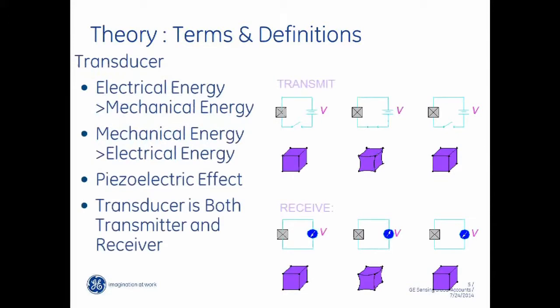So the actual transducer is nothing more than really a piezoelectric crystal that we energize and turn into mechanical energy, which is the wave itself, that then travels through the fluid to the receiving transducer. We clock how long that takes to happen, and we send a wave, actually a series of waves, back to the upstream transducer. So these transducers are senders and receivers. In essence, it's like us talking back and forth on a phone call and clocking how long it takes for our voices to carry that distance.